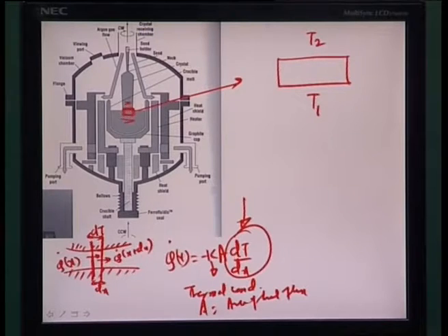Now you are seeing here that there is a temperature gradient, and therefore there should be a heat flow. On this side, you have the zone of fusion, and a certain heat flow Q1x from the liquid into the zone of fusion, and on this side a certain heat flow Q2x from the zone of fusion to the solid zone.